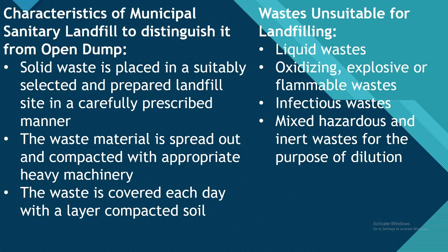So the first one is solid waste is placed in a suitably selected and prepared landfill site in a carefully prescribed manner. The waste material is spread out and compacted with appropriate heavy machinery. The last one is the waste is covered each day with a new layer of compacted soil.